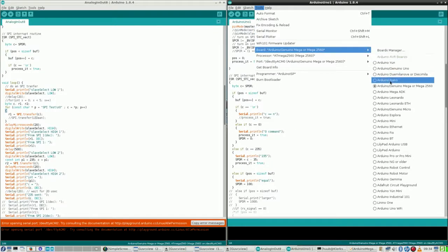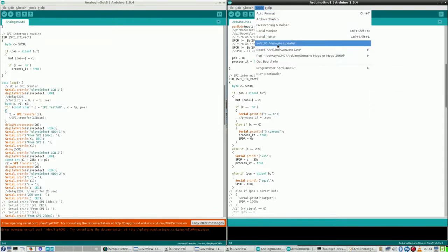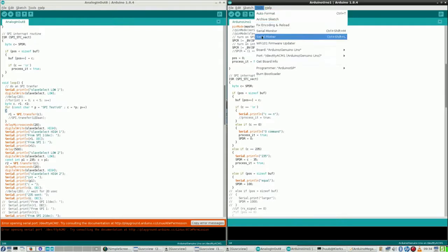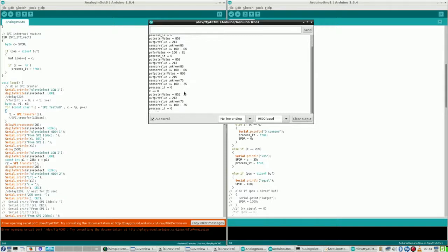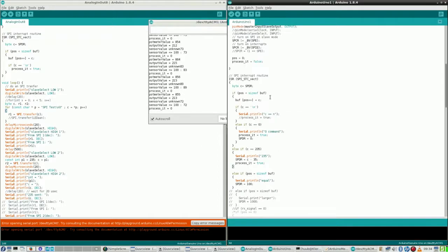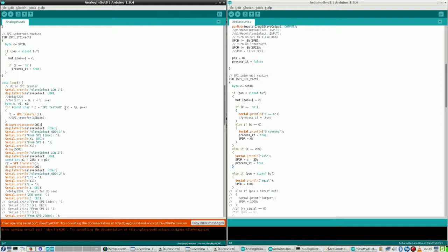Because if I look here, closing this one, then I have to select Uno and port Uno, monitor, then I get absolutely nothing anymore. So the whole thing being tested from SPI, whatever it should be, is gone. Why is it gone? Here, it should have been printed somewhere. So two things to do. One, printing on the serial monitor what the content of C is, and here getting SPI test printing on screen again.